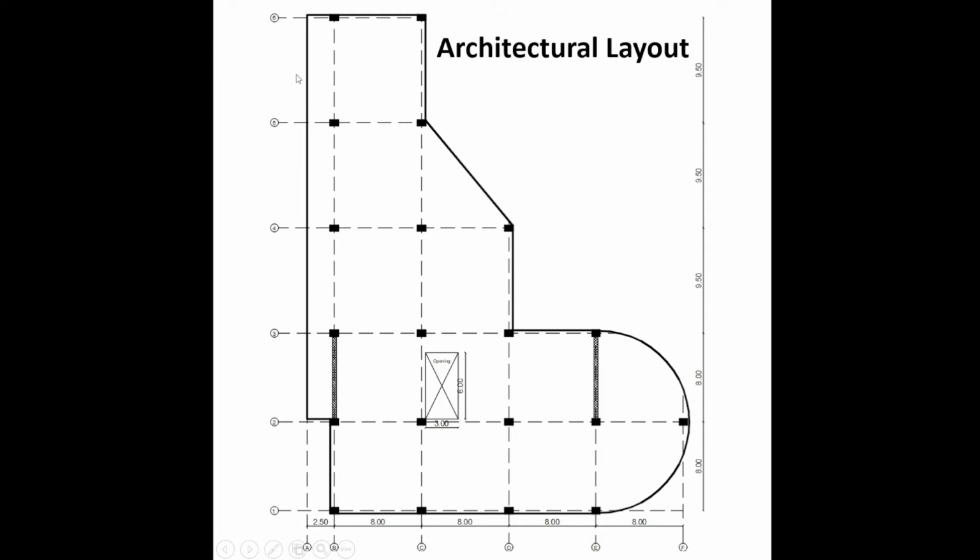So in these spans, external beams will be applied only for its weight and for a perimeter wall of 6 kN per meter, also some portion of the slab, according to tributary area, as we will explain later.